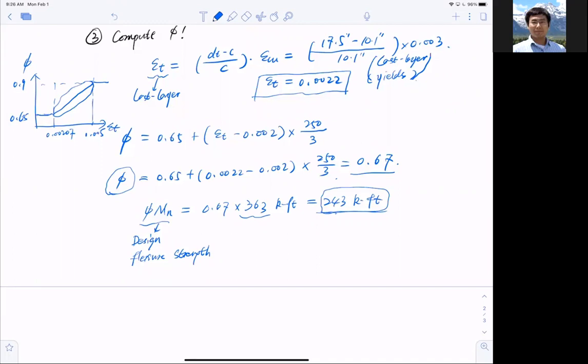All right, so I just want you to keep in mind that whenever you design out there in the firm or the company, or whoever you work for, when you're trying to design a section, don't just blindly throw reinforcement in it to make the section stronger. Don't do that, because it may not work sometimes. So more reinforcement, I want you to remember this, more reinforcement doesn't always guarantee a higher capacity.